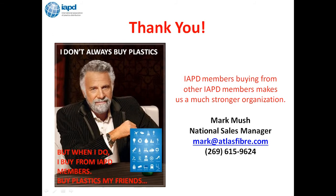But in general, yeah, I don't think I would want to put a phenolic part, canvas, linen, paper, submerged in water unless it was a specific specialty grade like the canvas marine grade, which can take very high humidity applications. But again, to be submerged in water, probably not the best application. Okay.